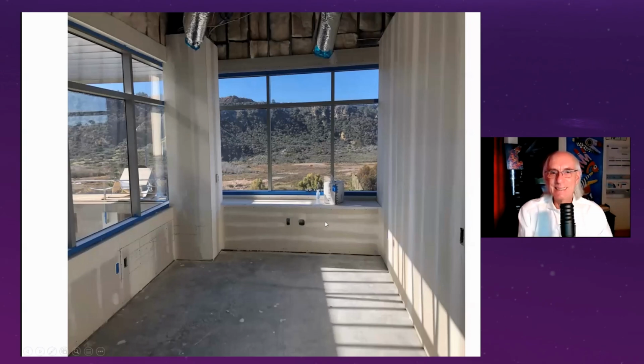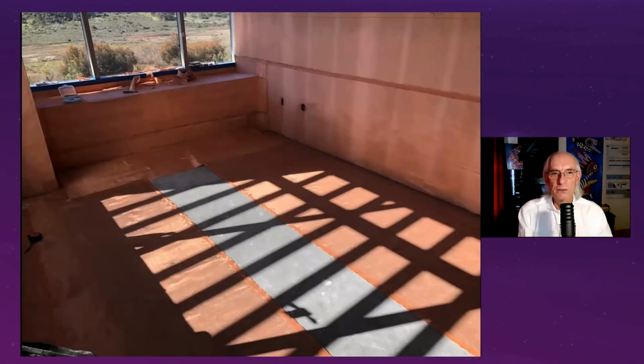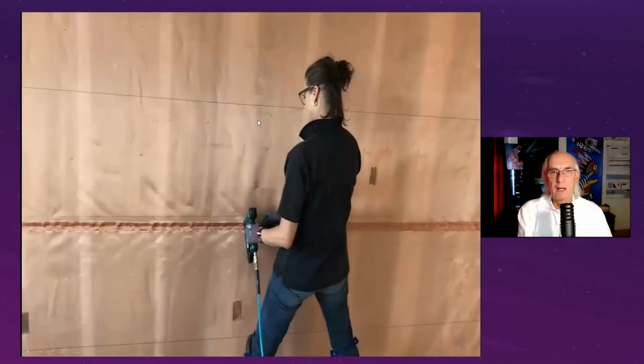So the antennas are sitting in this bump out here, which is basically the window sill, and half the antenna is on this floor and half the antenna is on the floor below. So this is where the doctor is going to sit right here with his back about a foot or two from the antennas. So what can we do? Well, we applied shielding materials to the walls, to the floors, and especially to the bump out area, where we actually put 2 layers of shielding material on there to create a reduction.